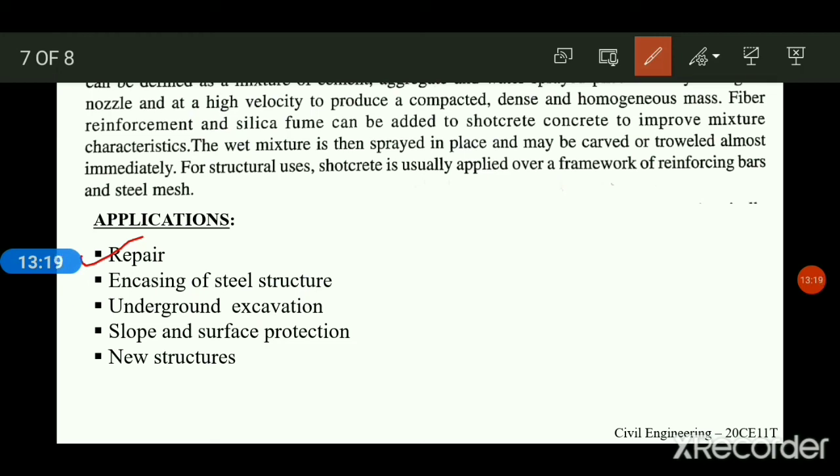It is useful for repairing beams with variable depth, columns and abutments. It can also be used for repairing fire and earthquake damaged buildings, and to strengthen and repair deteriorated concrete surfaces. Sometimes it is used in tunneling to bind the walls of the tunnel to prevent leaks and fragmentation.